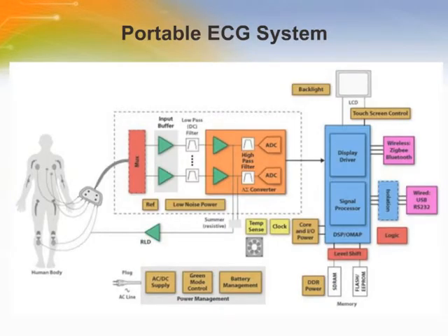One application of particular interest for the INA333 is portable ECG systems or heart rate monitors. In an ECG application, the action potential created by the heart wall contraction spreads electrical currents from the heart throughout the body. This creates different potentials at different points on the body, which can be sensed by electrodes on the skin surface.